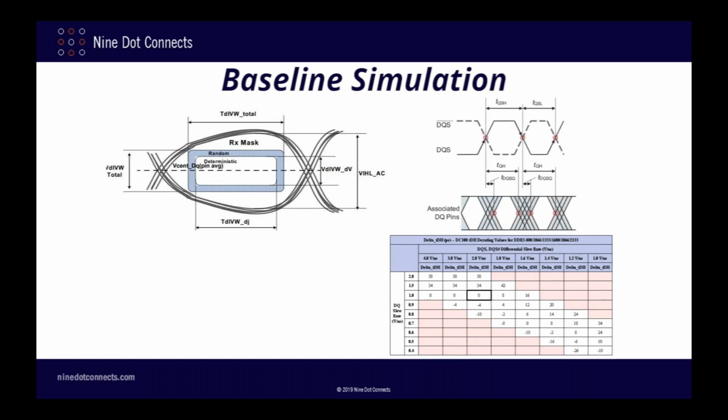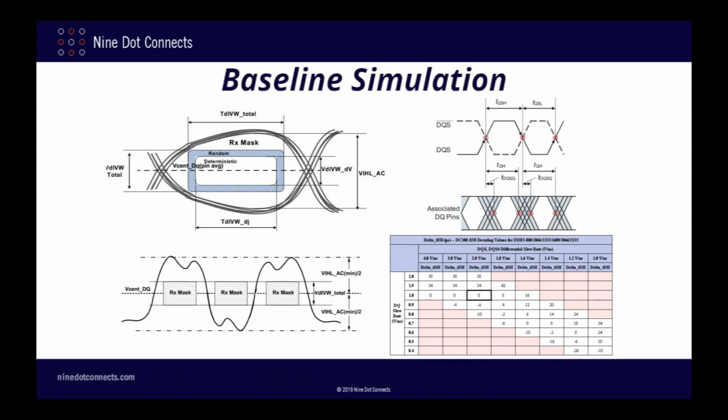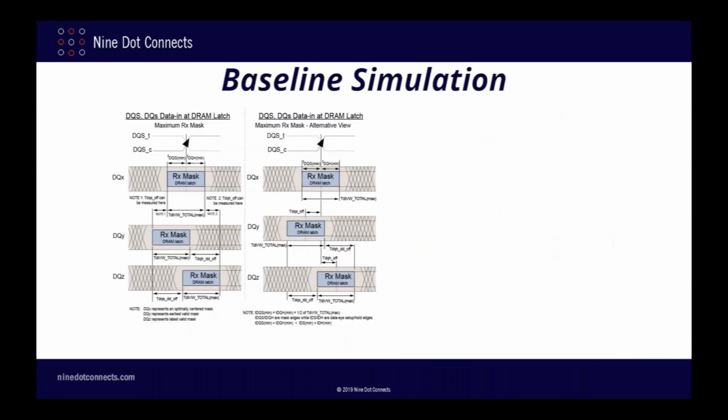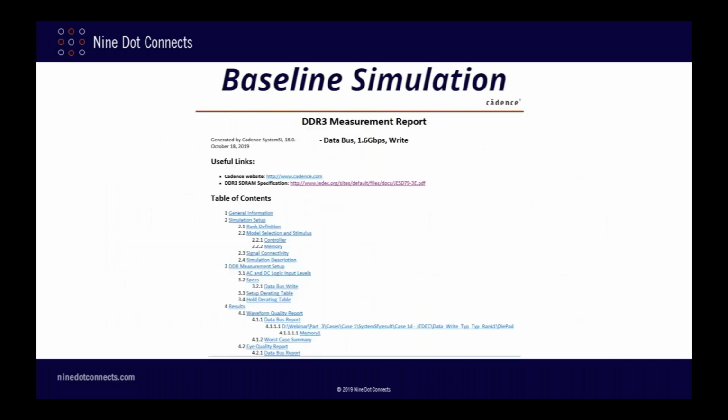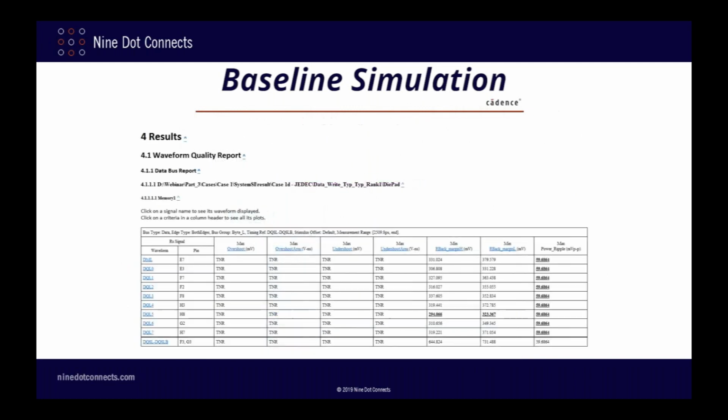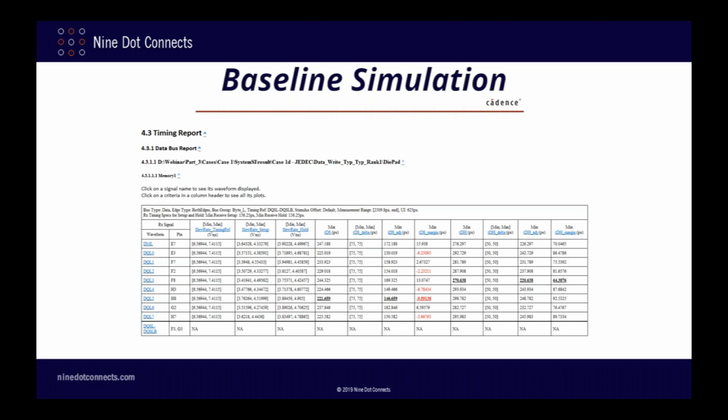We are also fortunate that providers of simulation tools recognize the need to meet JEDEC standards, and have incorporated these standards into their simulation tools. So instead of having to manually interpret the waveforms and numbers generated by simulation, the tool generates a JEDEC compliance report for us instead. This extensive report is in the form of an HTML document and contains an exhaustive analysis of the design. Unfortunately, it is not in a format that lends itself well to my webinar display process, so I'm only showing a few sections of the report as examples.